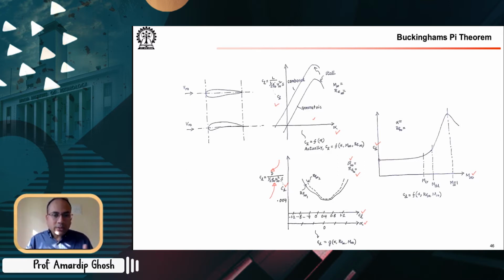So for example, Reynolds number, Mach number, Prandtl number, these things fall out from the second approach, where you start with normalizing and non-dimensionalizing the terms in a PDE or ODE, or we say the governing equations. On the other hand, from Buckingham's Pi theorem, you get the pi groups. If you know that these are the physically relevant pi groups, by the choice of the repeating variables, etc., you can generate pi groups that are eventually, like a drag coefficient, Reynolds number, etc.